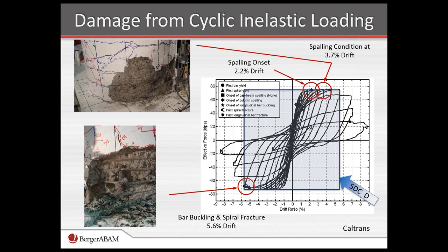Now, in our design category D, say the highest design category, we would expect to essentially fully utilize that displacement capacity, the ductility or the deformation capacity in the inelastic range. But in the lowest category, in A, we really expect to have just barely, perhaps a little inelasticity as shown in the red box, but essentially just mobilizing the lateral strength of the system, but not the ductility.